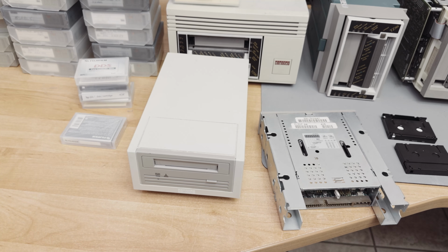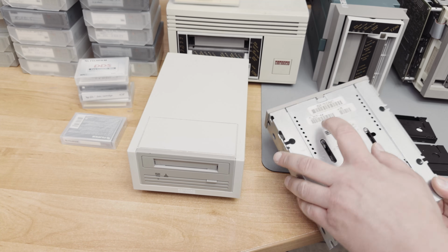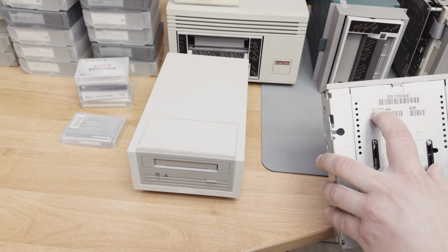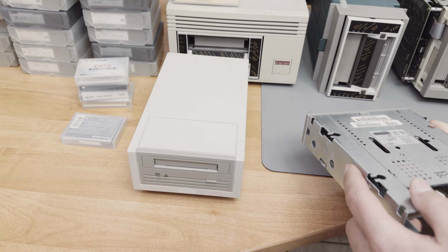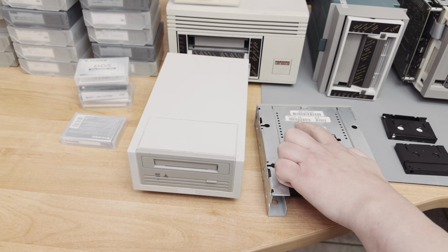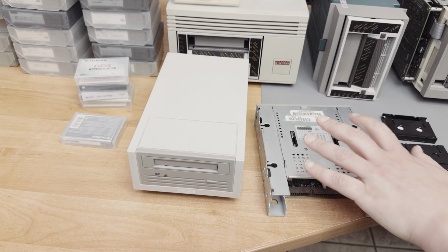I have, as I said before, DAT and DLT, and I want to start with the DAT drives, but before that I want to talk about the last letter, because it shows the connection. A Z shows that this is a SCSI drive. If there is an F, then it's a DSSI drive, and if there is a K, then it's a drive with a dedicated controller. I will show all 3 kinds of tape drives in this video. Let's begin with DAT.